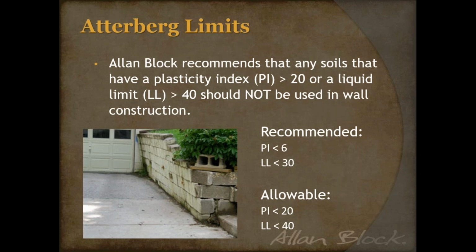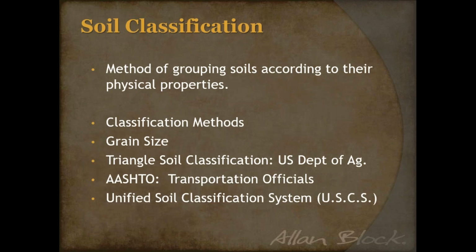But once we know the particle size and the plasticity index, especially when you're talking about the unified soil classification, you can qualify the type of material you have. Now, there's different variations of this. I show this here, and even different countries that we have on the call use different versions, but they're all basically rooted in the same options, which is the soil size and properties.